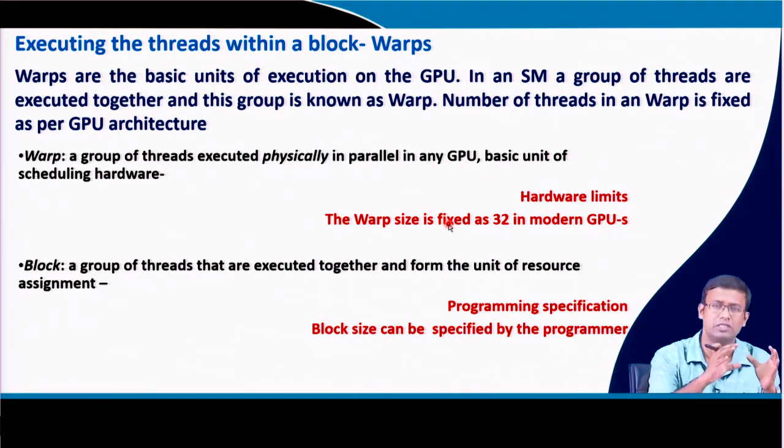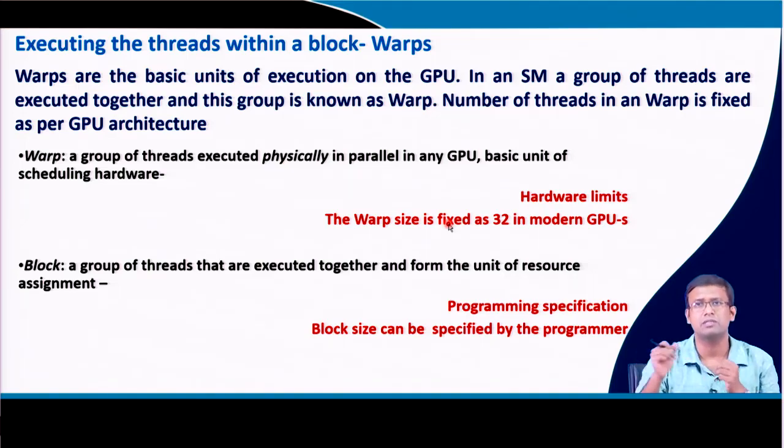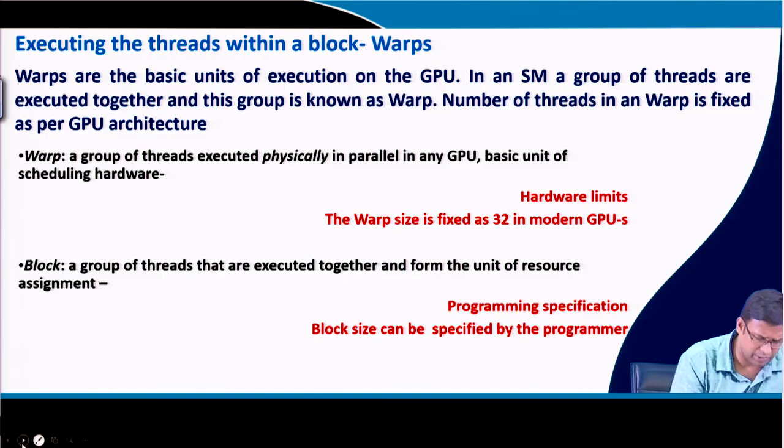So when a GPU program runs, the streaming multiprocessors also work in parallel, but one block goes to one streaming multiprocessor, and inside one streaming multiprocessor only 32 threads are chosen and active at one point of time, and then the next 32 will be chosen, and that's how they are scheduled. If your number of blocks is less than the number of streaming multiprocessors, you are losing, because some of the streaming multiprocessors are inactive. Also, if your block size is less than the warp size, then you are losing because some of the cores are inactive. These are two very important aspects.